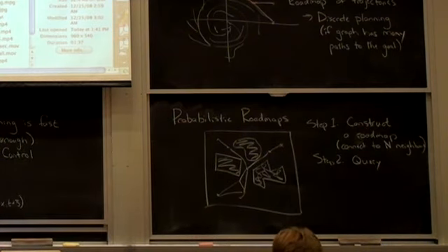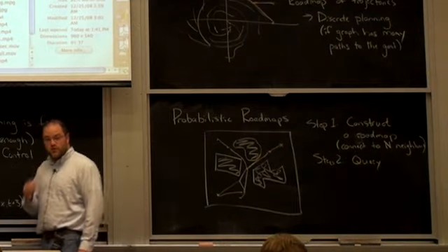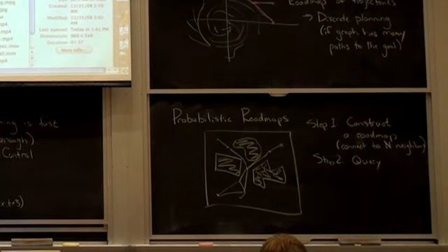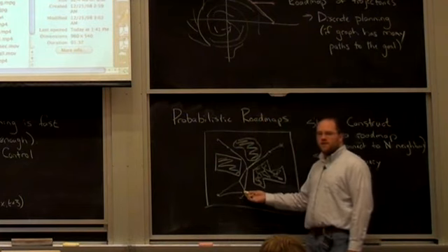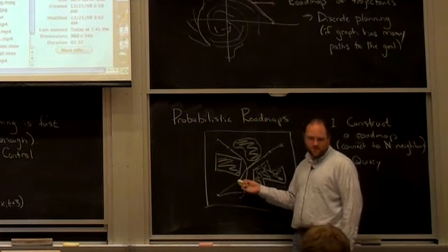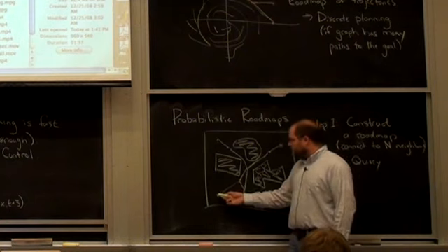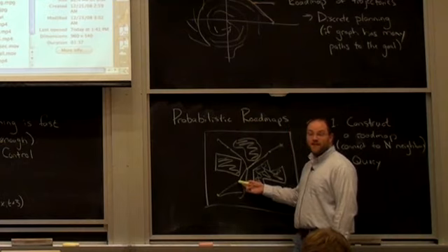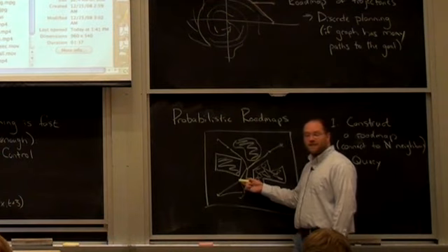I actually think it's a very beautiful idea to have this web of possible trajectories covering the state space. And then all it takes at execution time is connecting and then executing your trajectory. Now with probabilistic roadmaps, the step of connecting nearby points in underactuated systems might be hard, might be as hard as finding the path from the start to the goal. So maybe what you do here is a dircol or something to find that path, or you do an RRT, or any of the other methods we've done to make these initial connections.